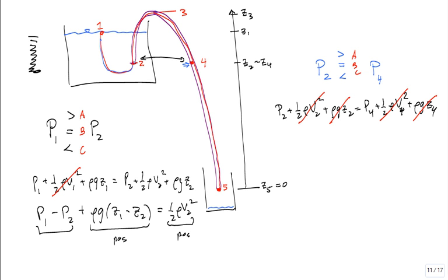All right. Okay, so I think I already mentioned this. Once you have the speed at 5, which is the same speed at 4, same speed at 3, same speed at 2, then you multiply it by the density and the area, and you get the mass flow rate. How do I increase the mass flow rate of the siphon? I can either increase the area, or I can increase the speed by increasing the elevation difference. True? If I wanted to, I can increase Z1.